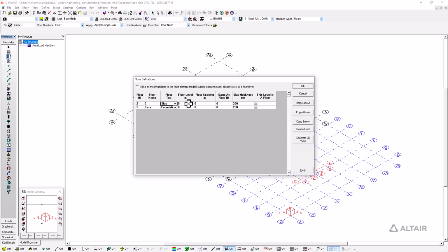And so I'm going to set up basically floor plans to help facilitate that modeling. I'm going to say that this floor for the bottom is 5 meters high, and I'm going to toggle on this as a level as a floor option, which will allow me to basically treat not only the slab, but the columns and beams that are underneath that as a single floor.